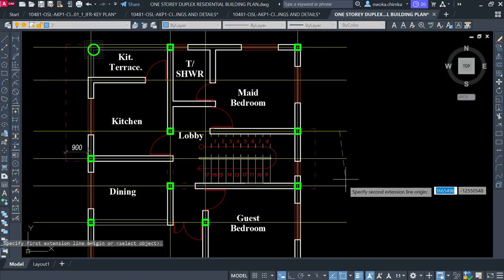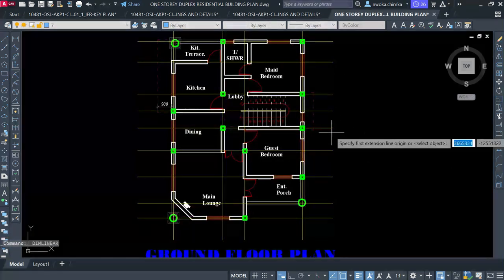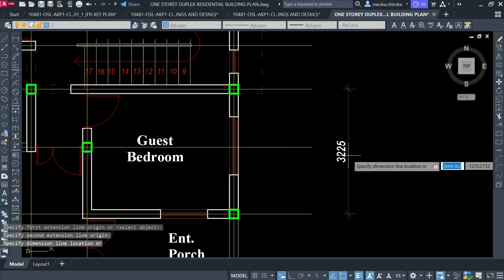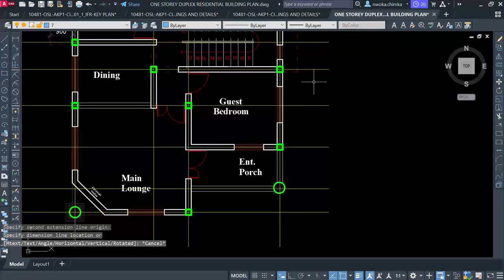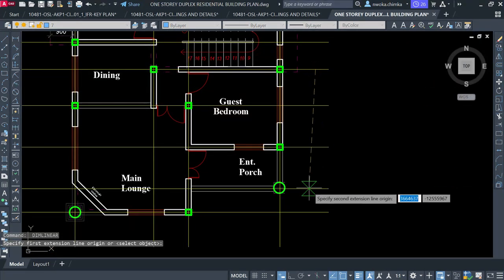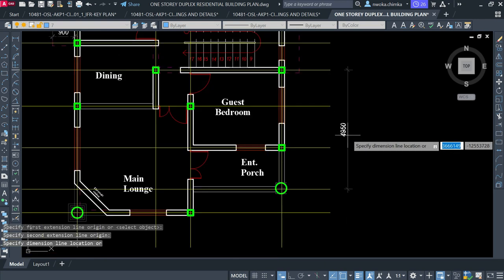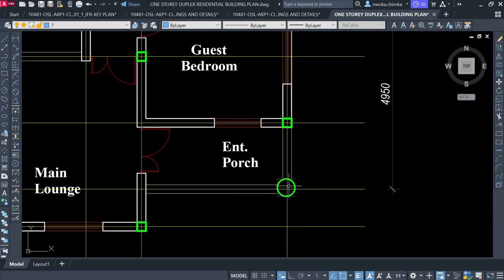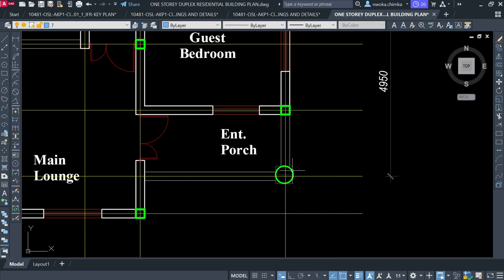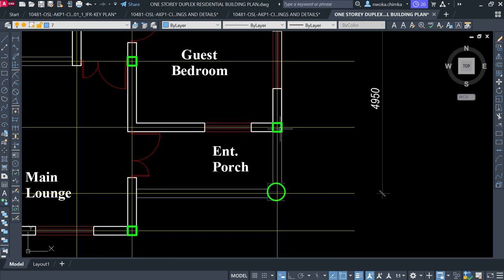Okay, so from here to here is also still below 6 meters, and from here to here is below 6 meters. Now, basically, most people will say, why am I putting this column here? Why not just span the beam from here to these points? As you can see, this is 4 point something meters, right? Now, I always advise people, whenever you have a fancy column, a column that came with a plan to give beauty to the building, always establish a structural column nearby. When I say structural column, I mean a column that will be able to hide inside the wall nearby.